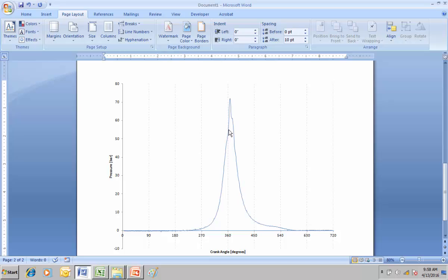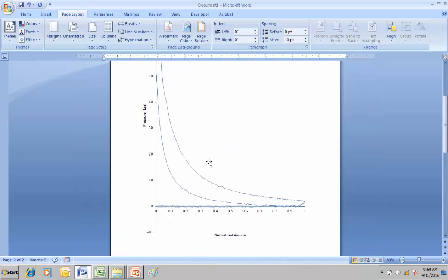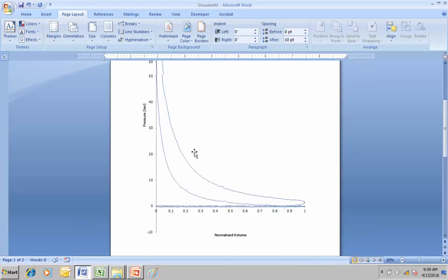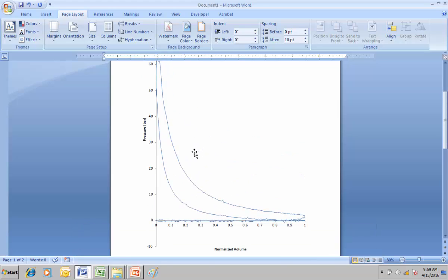And then that constant volume heat addition is going to end right here. So maybe 3A is right here, and combustion maybe ends over here for 3B. But it's going to be something similar there, where this is approximately where 2 is, 3A is something right around here, and 3B is something along there. I'm just trying to give you a better explanation than is in the lab write-up, the lab instructions.